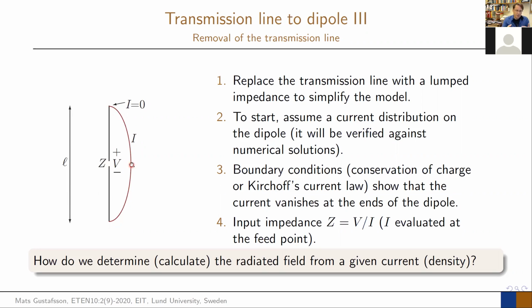And what we do now is remove the feed entirely, as I showed with the pictures of the dipole. I just say that here sits a voltage, so this antenna is fed by some voltage. This voltage represents everything that would happen in this twin wire that comes into it. So we make a simplified model. It's a very good way of doing it, because the input impedance of the antenna models the antenna as seen from the transmission line and circuits, and what's outside of it takes care of the radiation.